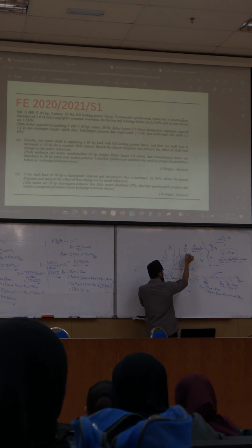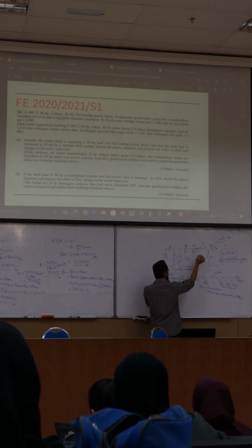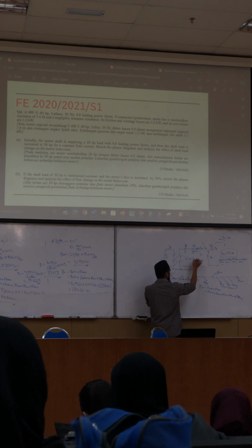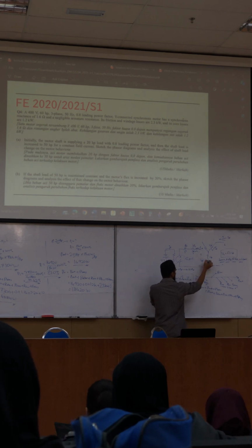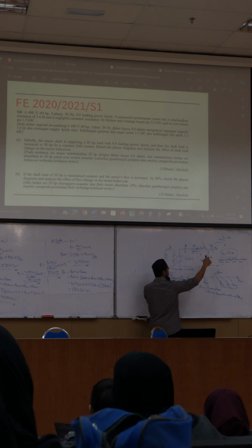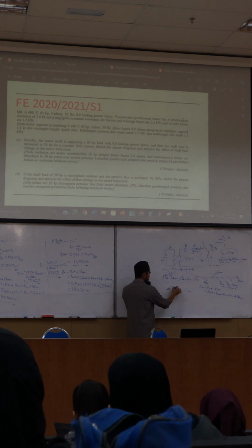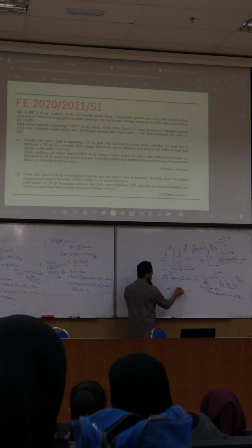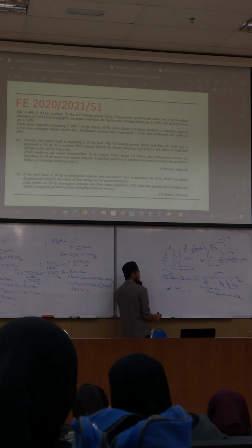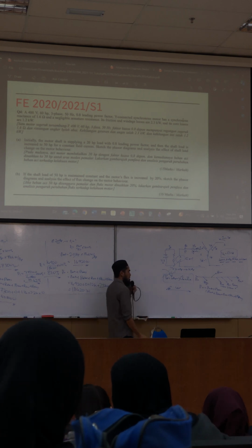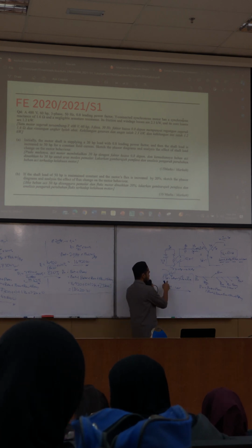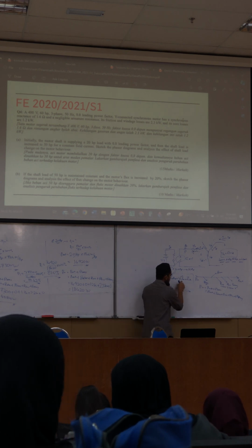We have been given RA and jXS, so the unknowns are EA, the phase voltage and phase current. The phasor diagram starts with V phase. For a motor it's quite tricky. Earlier was the generator. For a motor, V phase is the sum of IA RA plus jXS IA plus EA.